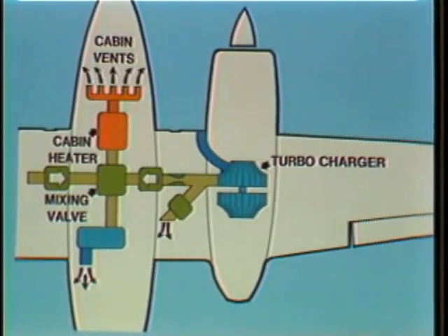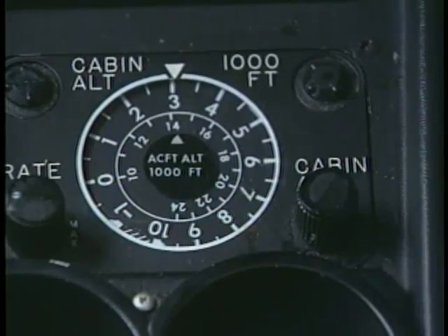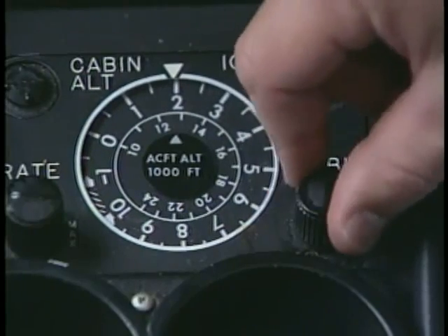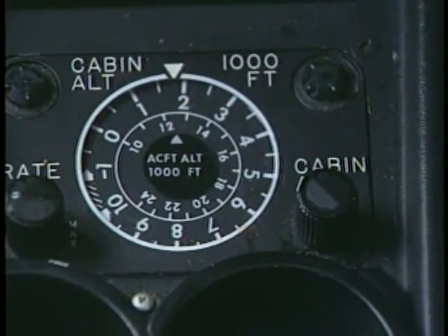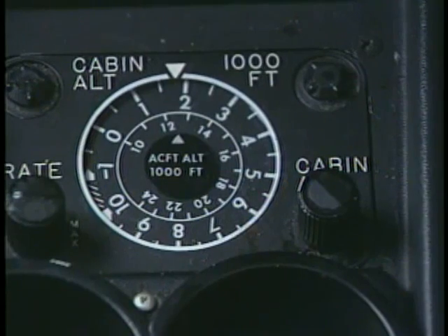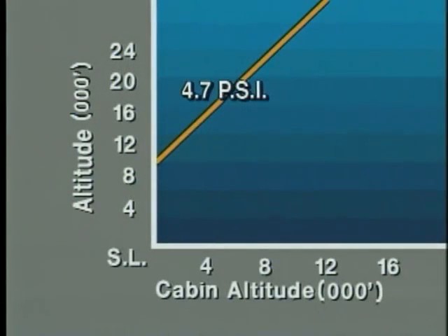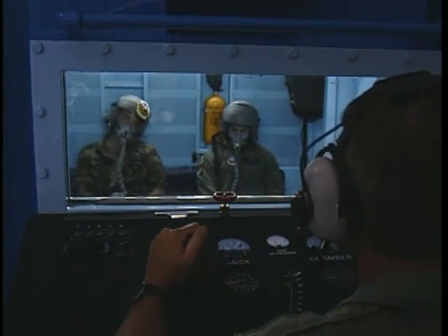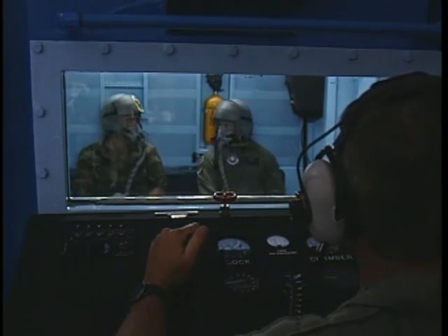For example, in most pressurized light twins and singles, pressurization is supplied to the cabin from the turbocharger's compressor or from an engine-driven pneumatic pump. The cabin altitude is manually selected and can be monitored by reference to a gauge which indicates the pressure difference between the cabin and ambient altitudes. Each aircraft has a maximum differential between cabin and ambient altitudes that the pressurized section of the aircraft can support. Decompression can occur due to a system malfunction or result from structural damage to the aircraft.